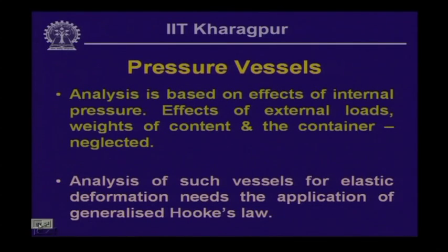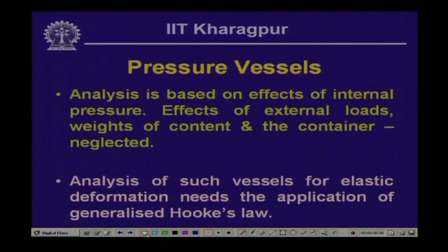Now, also in pressure vessels, when we try to analyze, we go for a simplified analysis, and this analysis is based on the effects that the internal pressure exerts, the forces on the body, and thereby the body is subjected to stress. That is what we try to analyze: how much stress the body undergoes when the container is subjected to pressure.